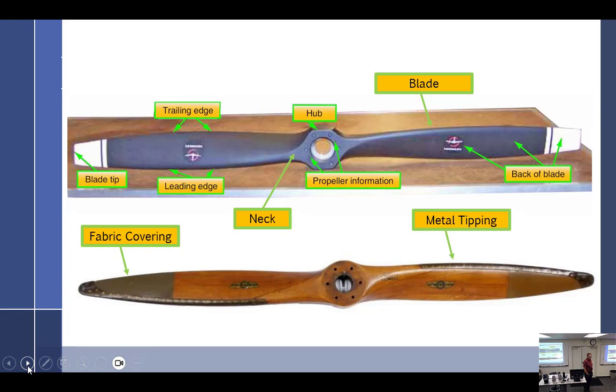So as a mechanic standing in front of the airplane, looking at the airplane, you're now looking at the back of the propeller. The pilot is sitting in the seat, getting ready to go flying. They're happy. They're looking at the face of the propeller. So the face of the prop faces the pilot. But what about if it's a pusher? Oh no, it's the same thing. You can turn around, the face faces the face.